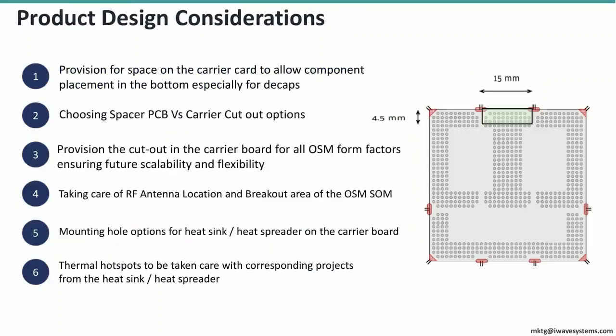So I'm going to run through a few of the design considerations, whether it's on the carrier board or on the SOM, whoever develops it. There are some areas you can look at. One of the things is the provision of space in the carrier board for accommodating the SOM bottom assembly. We have done some experiments with the decaps on the top and also on the bottom. Obviously, we settled on decaps on the bottom, especially directly on top of the power pins, which gives very good switching efficiency. So we would prefer the decaps mounted on the bottom, in the areas where a cutout is given.